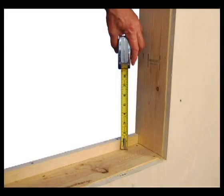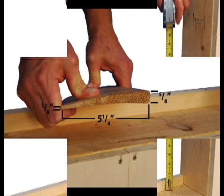The first step in the installation sequence is the back dam. The back dam is a low maintenance, moisture management technique to create an elevation change. The back dam can be made of a variety of material. In this case, we are using a 1" by 3/4" piece of wood stock that is nailed to the sill.